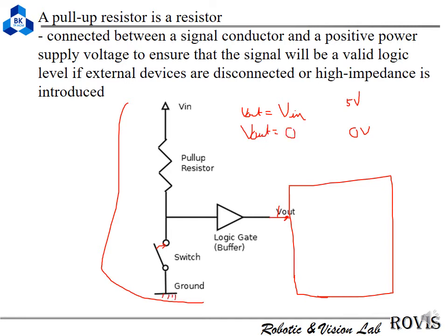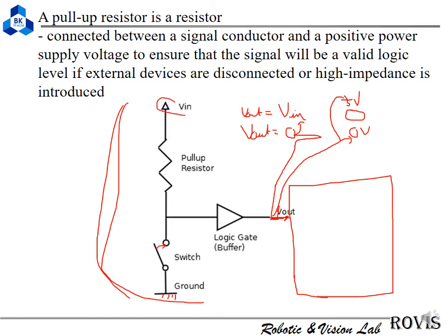So that means with this configuration, we make sure that this pin just receives logic 0 and logic 1, that means just 0 voltage and maximum voltage. We don't receive any voltage in between, because if we did, it would make the microcontroller work unstably.